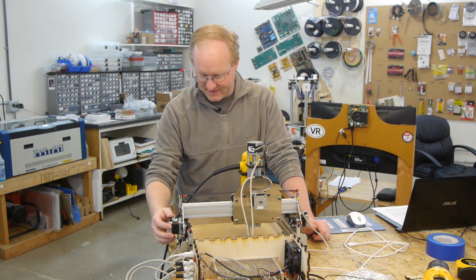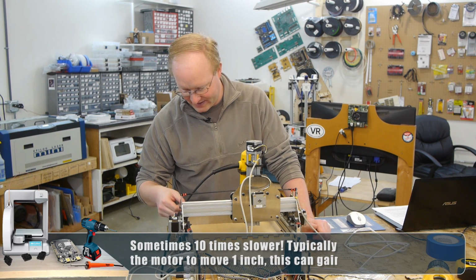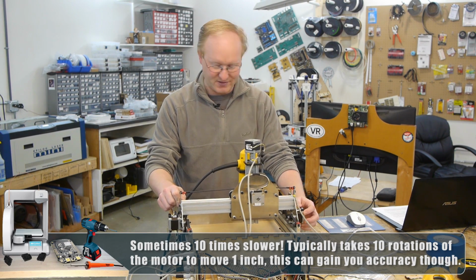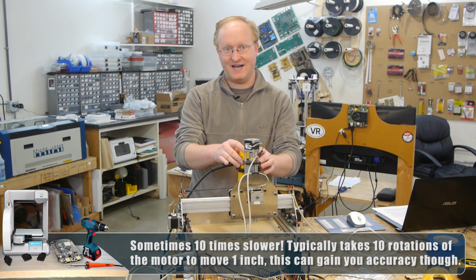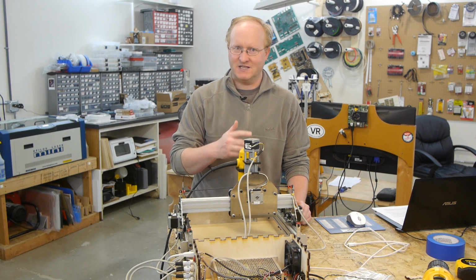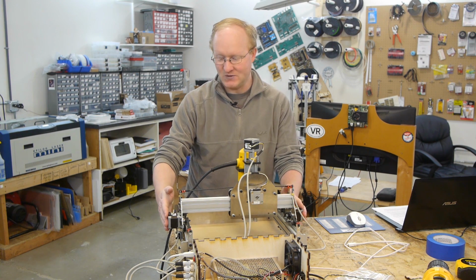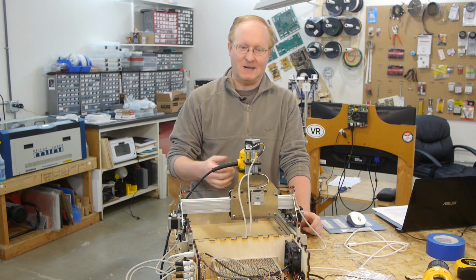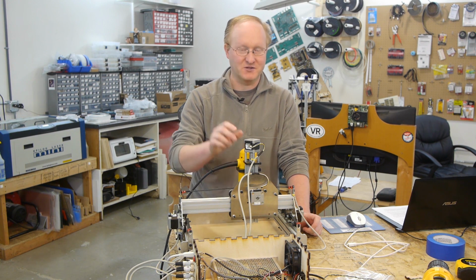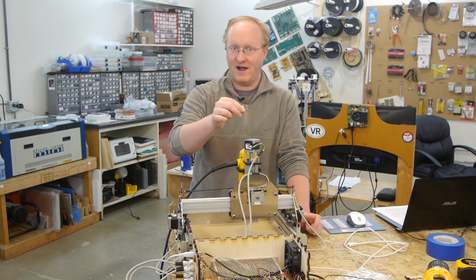But this belt system that they have here, it's a pretty affordable way of doing it. As long as you keep everything tight, it should be okay. Although you want to be careful with your torque. If you try to move this too fast, the bit won't be able to cut the material quickly enough, and this will bind up. Basically, it will be the failure point, and you'll lose steps, which means the machine won't remember where it was. So if it makes a circle, it won't return back to the correct spot.